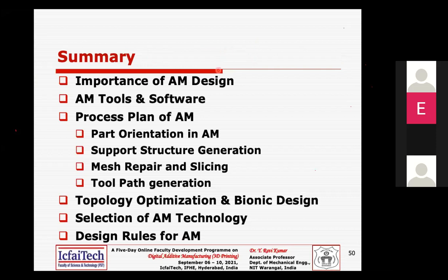What I have done for the past 1 hour 40 minutes: we started with the general introduction to AM, the importance of additive manufacturing designs, and the various tools and software used in additive manufacturing. We thoroughly discussed the process plans of additive manufacturing: part orientation, support generation, mesh repair, slicing, and tool path generation.